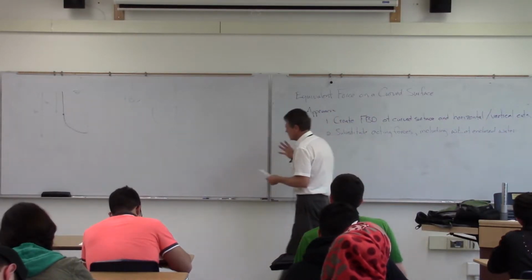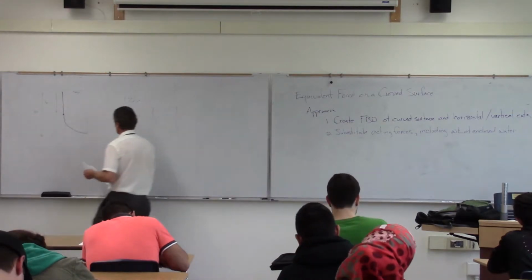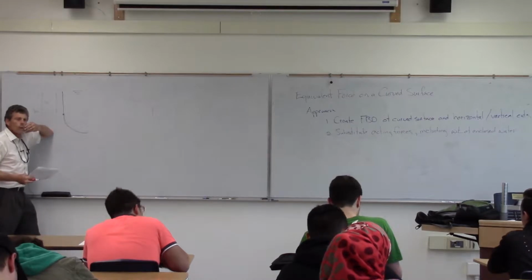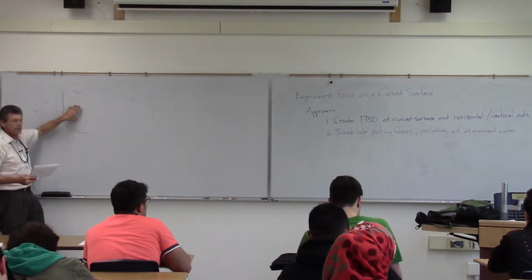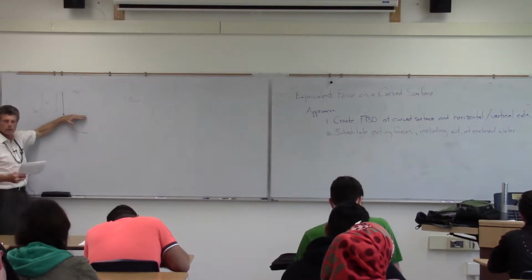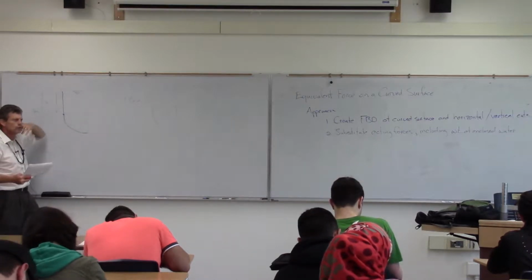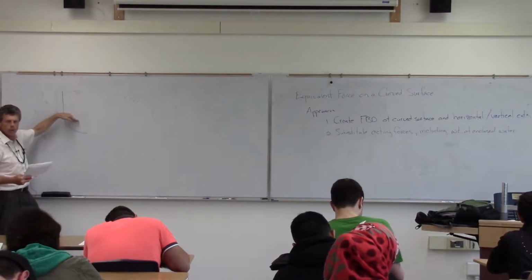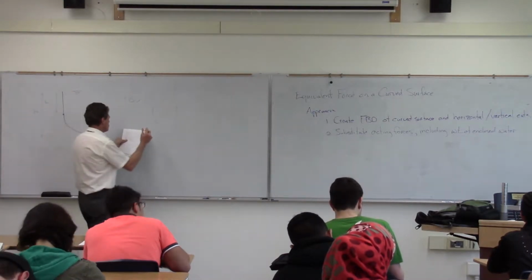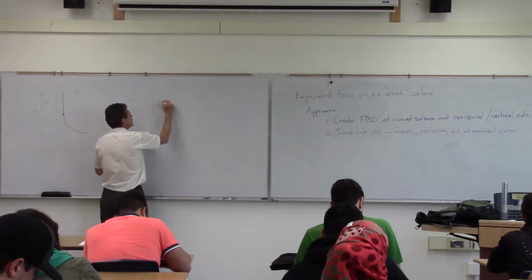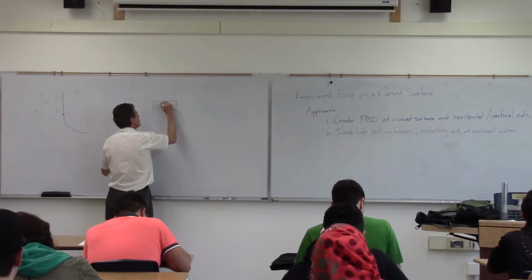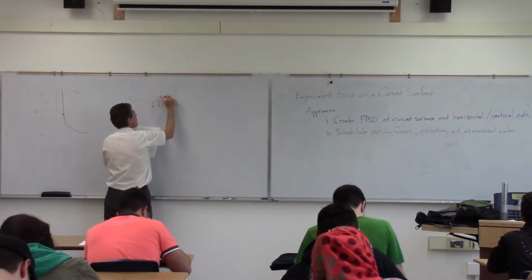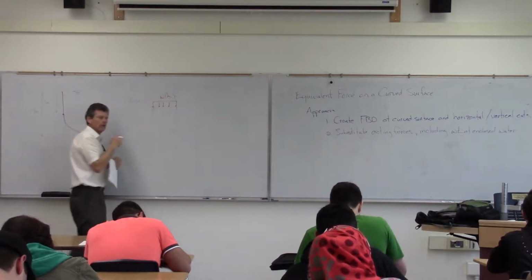Okay, so what we're going to do then is we're going to now substitute. We've cut this out, but we've got to think, okay, when we cut this out, there's going to be forces acting on this. When we think about this top surface here, this horizontal surface here, well, we've got all the weight of this water, this whole H1 of water acting on that. So in terms of what we're going to see here, the water sees this load of H1.